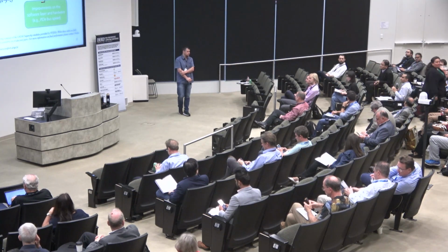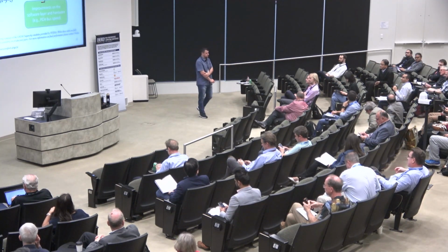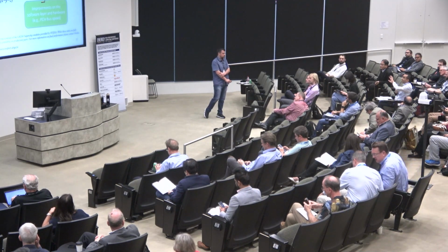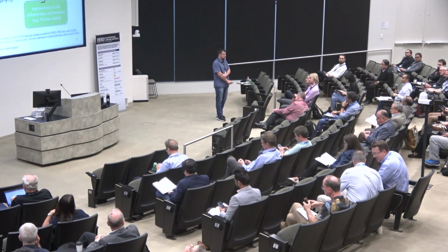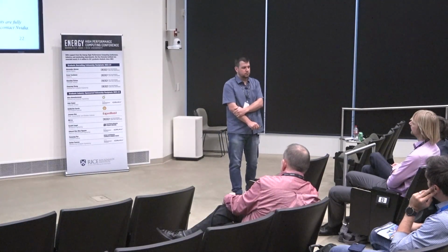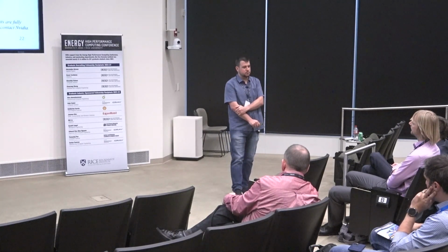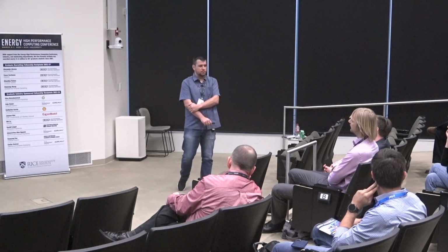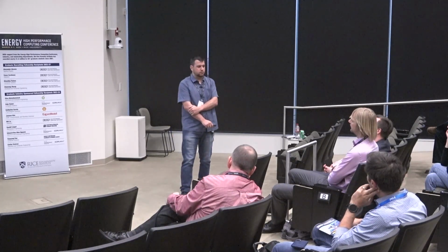Yeah, thank you for the presentation. I mean, you are comparing other generations that had PCIe, but the newer generation with the GH does not have PCIe. So how much of the uplift are you getting by having that big pipe connecting Grace and Hopper versus the previous generations, which were PCIe Gen 4 or Gen 3 or Gen 2, which was very low speed, like Gen 4 is about 32 gigabytes a second. But the newer generation with the Grace and the Hopper is 400 plus, right?